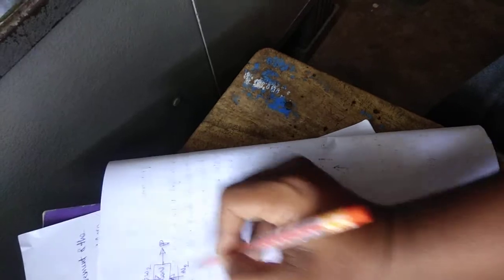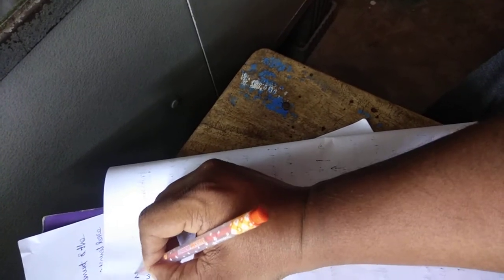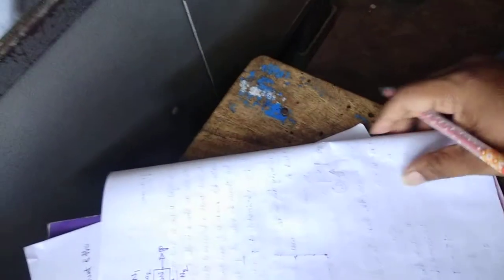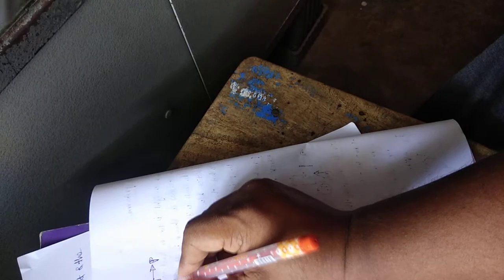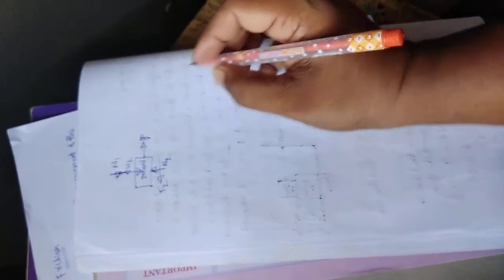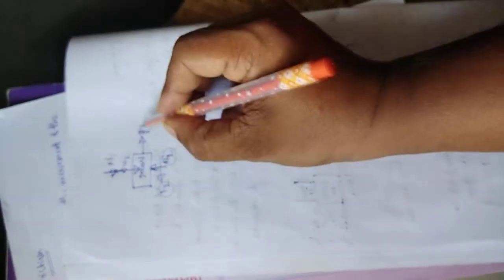As block A is lying on the 2000 Newton block also, we need to consider here the normal reaction force on the 2000 Newton block also. Now we are trying for the four forces: N2, F2, P and W2.